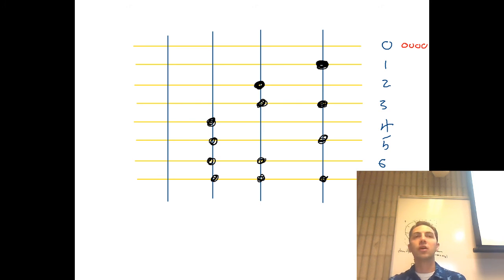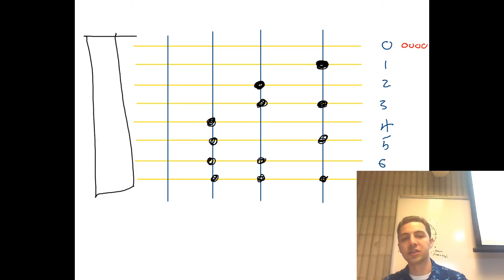So if you want to program a new chip with new firmware, let's say this instead of numbers was actually instructions in a program memory, you'd have to create a whole new mask. And that can be expensive. But if you're making a bajillion of these things, mask is the easiest way. Put the mask over it, shine some light on it, next chip, over and over and over. It's great for high volume manufacturing. Okay. There are other ways to do ROMs, but that's really the fun one, how to build up a mask ROM. And always over here, this is your decoder.